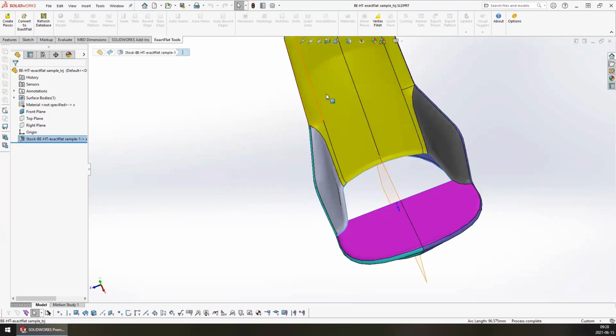We don't want to see a vertex somewhere placed in the middle of a very long edge. If you do that, downstream, once you start adding seams and hems, your seams aren't going to align, your notches aren't going to align, and you're not going to end up with a good pattern.